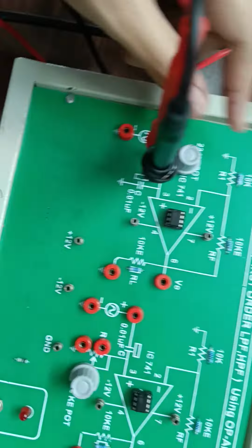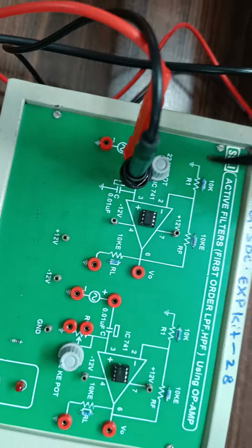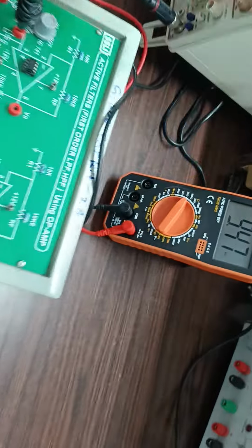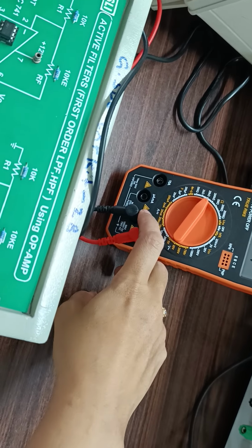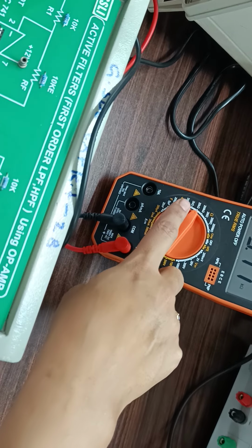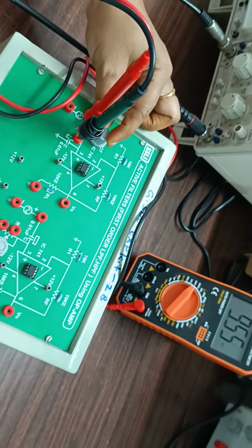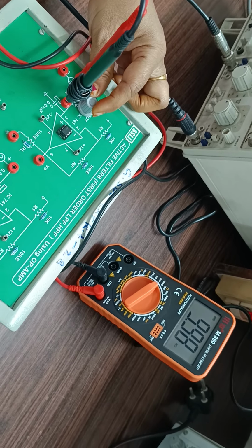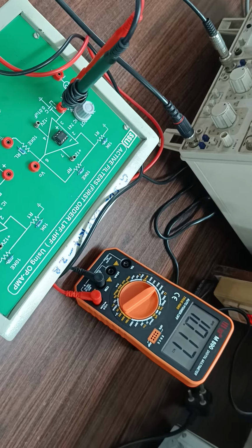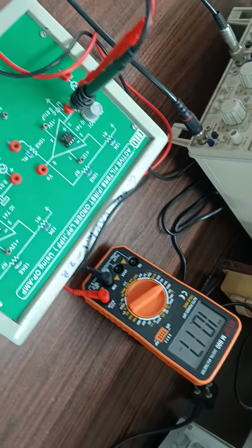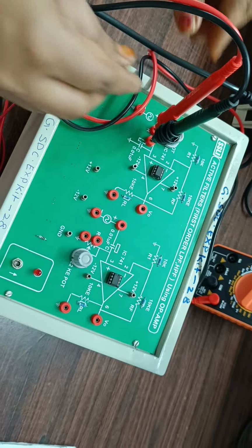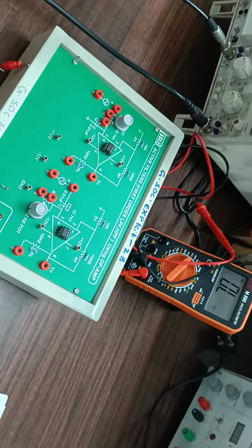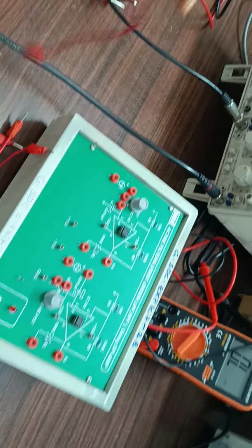10 kilo ohms. This is the potentiometer which ranges from 0 to 22 kilo ohm. So we have connected the probes of multimeter, and you have to keep it on volt, and this is common, and keep this pointer towards the resistance values and adjust the potentiometer and check the resistance value to be 10 kilo ohms exactly, 10 point something, 10. Okay, you have to do this adjustment before switching on the kit. You have to switch off the kit and make this adjustment, then remove it. Do not disturb the potentiometer value.